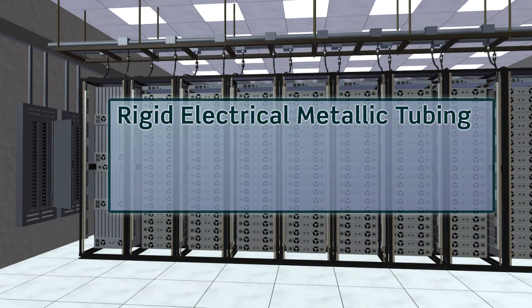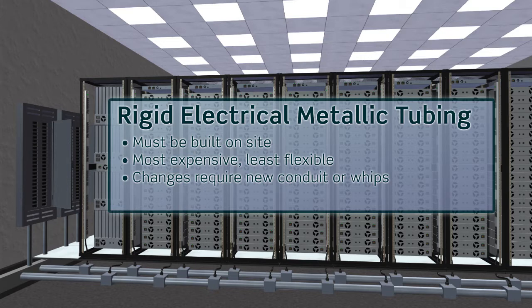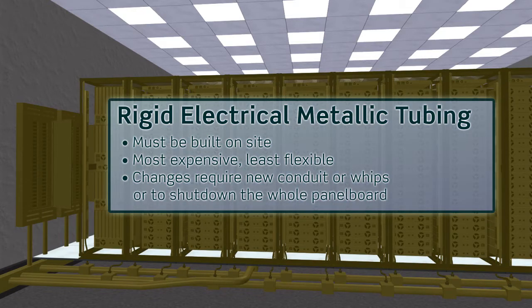Rigid electrical metallic tubing whips are the oldest and most traditional method utilized in the data center, and they were brought over from standard commercial building electrical practices. While it can be run overhead or under the floor, EMT must be built on site and cannot be moved once in place. It is the most expensive type of whip construction, yet the least flexible and adaptable method. Changes require either new conduit or whips to be run, and/or the panel board must be powered down to allow changes to existing whips.